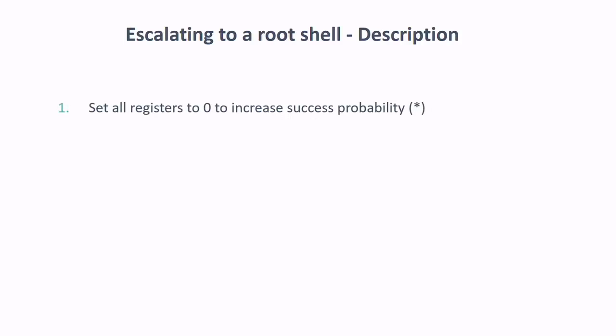Keep in mind that when you actually do a call to a function, there is always a result which is returned to the caller, like yes, true, or no, false, or something like that. This is usually represented with some binary value in the assembly, in the call. So we thought, perhaps if we set all the registers to this good value, we might have a situation where this value is actually returned to the caller by our glitch. We don't know how. So it would not be possible for us to say, hey, in this code we were able to. But we are able to say that statistically we have been able to affect that.